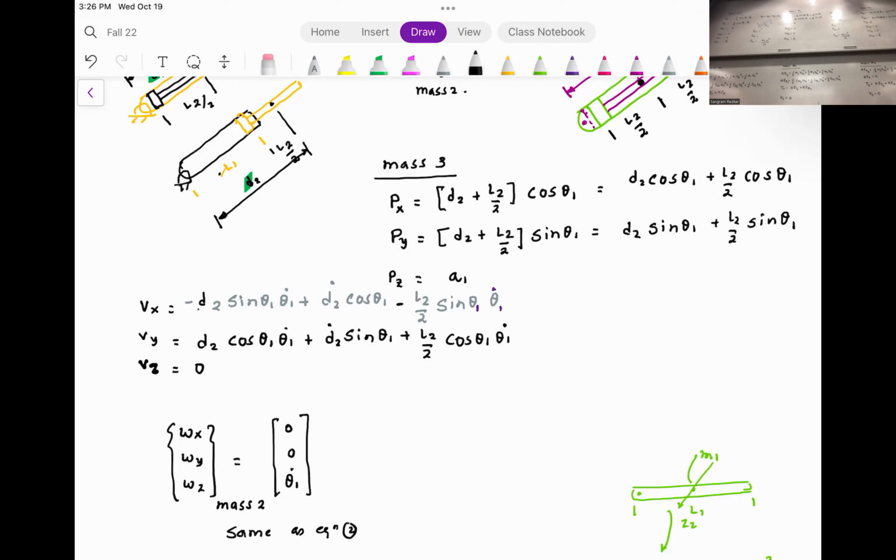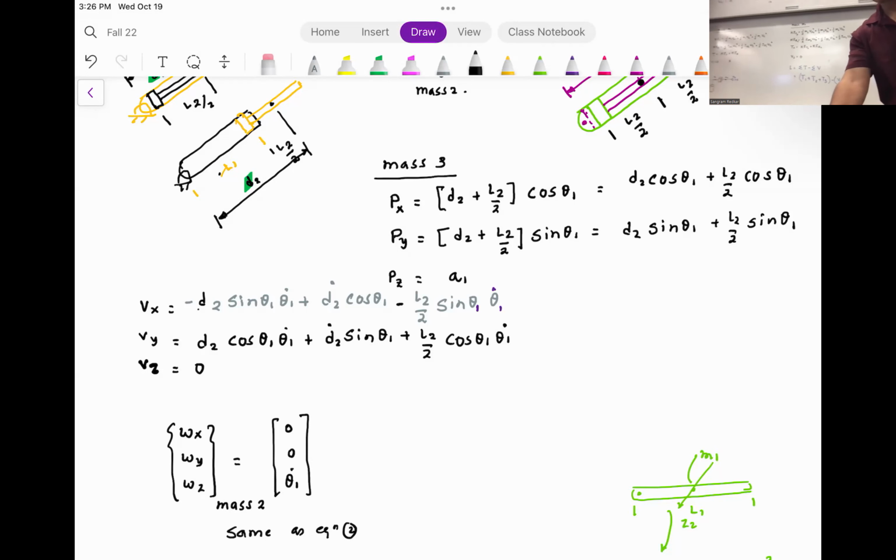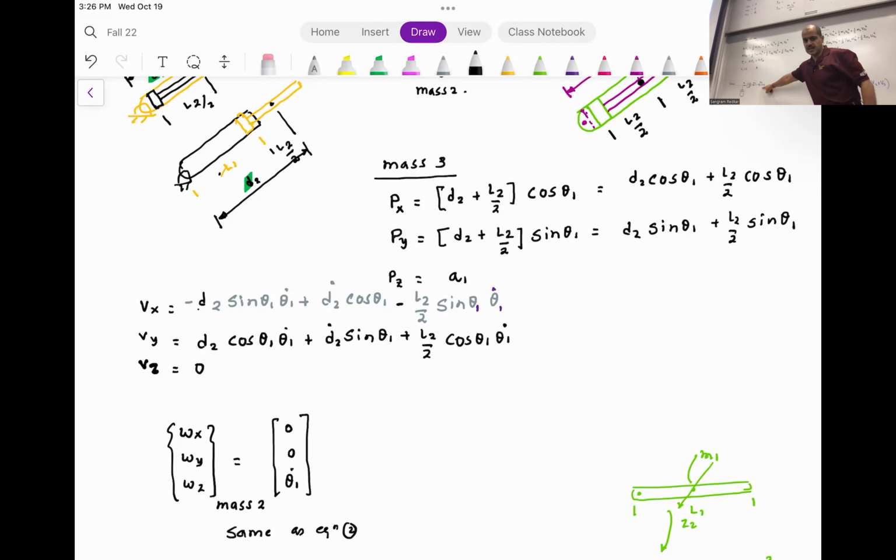And these equations are nothing but the same equations. The potential energies are zeros because, if you look at this, yeah, it's slightly askew, of course. Because masses M3, M2, and M1 are in the horizontal plane, and I am assuming the datum is aligned with M1, M2, and M3. That's why there is no potential difference. That's why V1 is 0, V2 is 0, and V3 is 0.